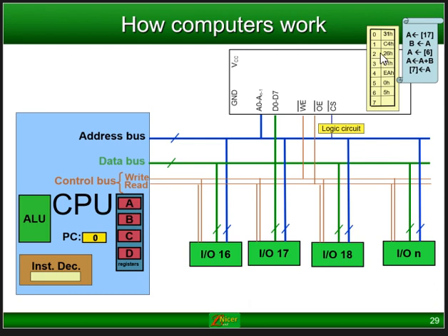This next instruction, which is instruction number 2, which is 26 hex, it looks like, means go to address number 6, take the content in there, which is 5x, there you can see 5x, and place that in the register A. And the next instruction actually says, listen, add A register and B register together.